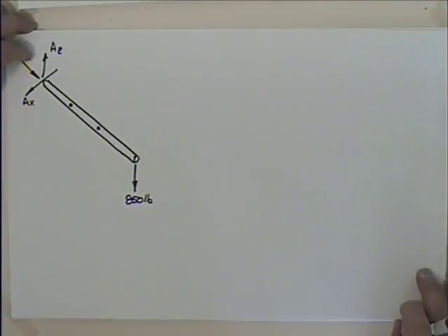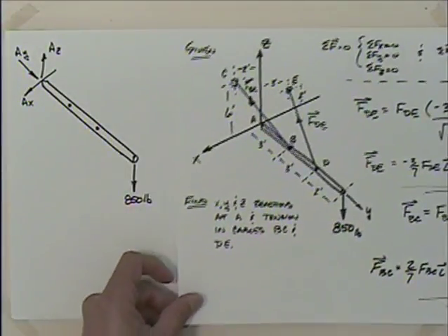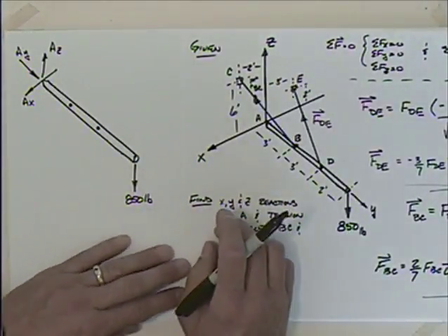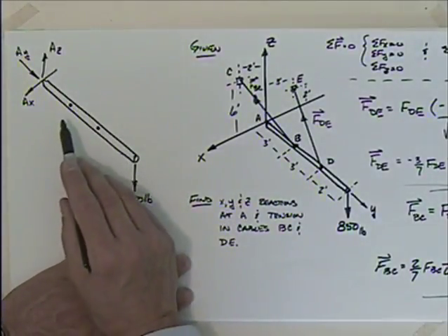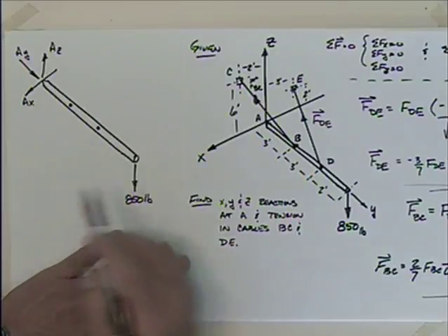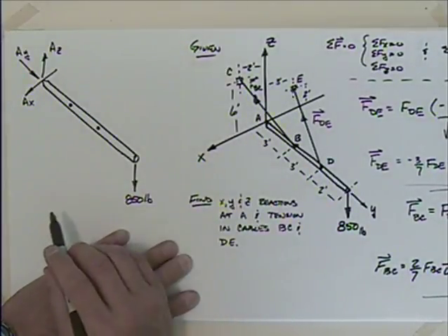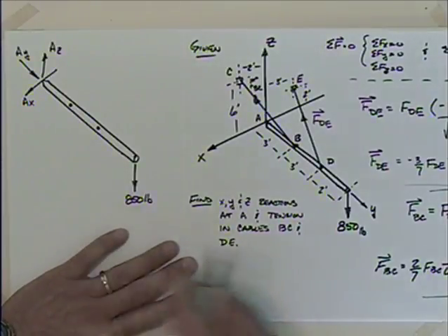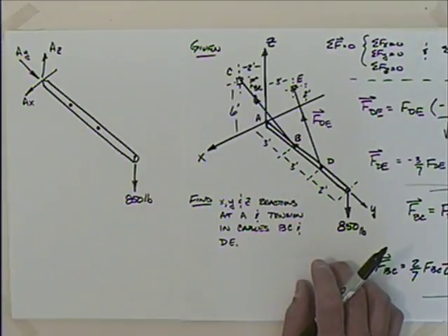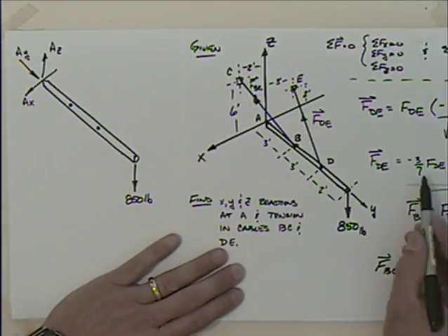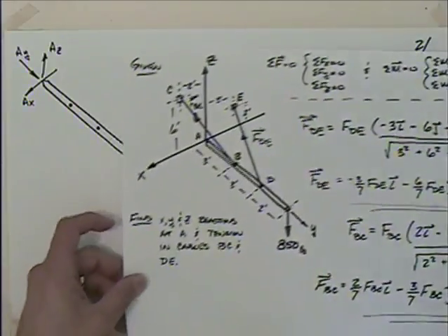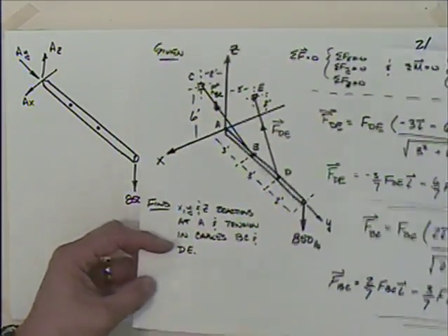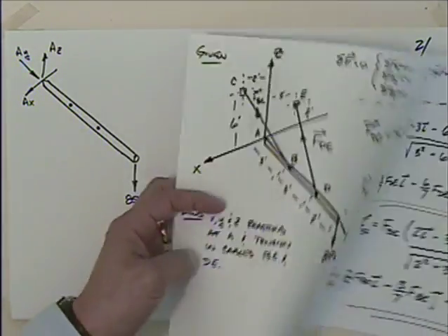And normally with free body diagrams, we like to put in all of the dimensions and whatnot, so it's all there. Although on this one, we can end up with problems because we can get so much information. So I'm going to refer back to the original drawing for the dimensions. I'm not going to put them in here because it can just get too cluttered. But normally we like to do that. And the other thing that I'm going to do on this is I'm going to put these forces in here. So rather than just putting BC up there, I'm going to break that into the pieces.